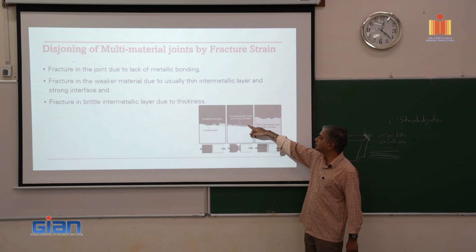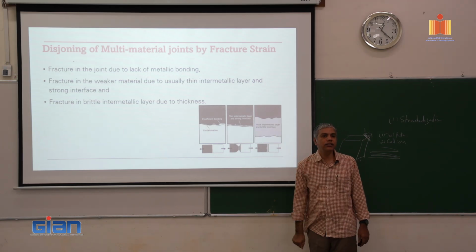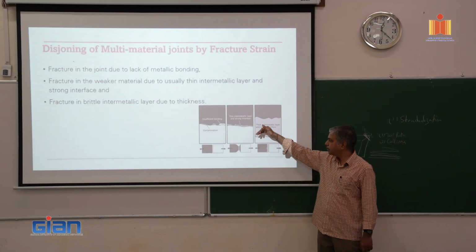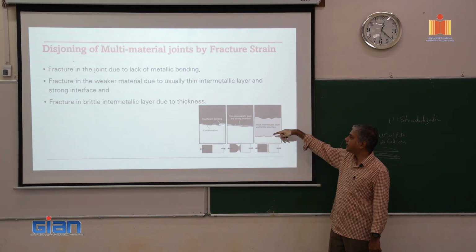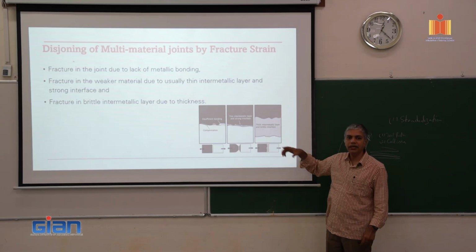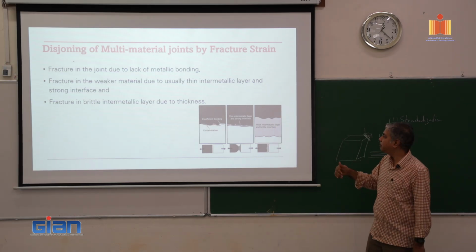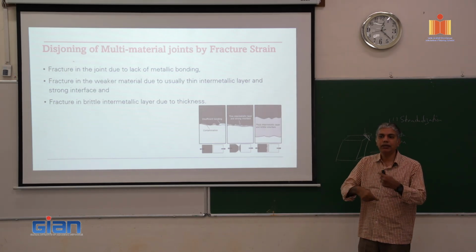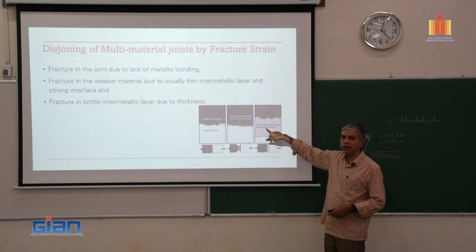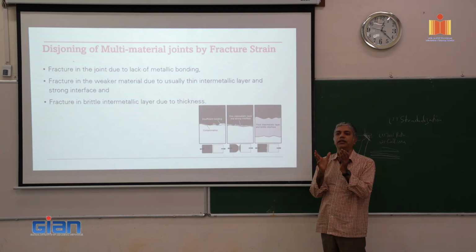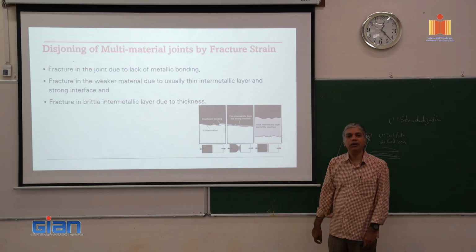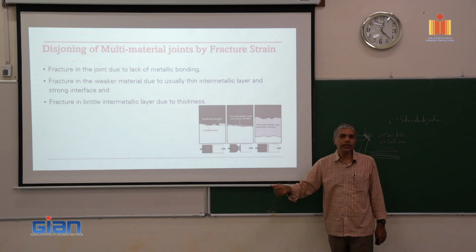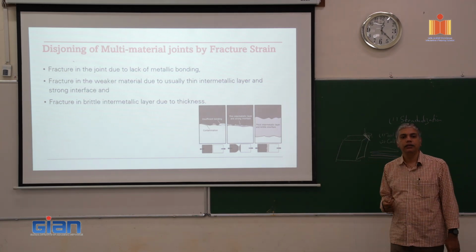In other applications, you also have an intermetallic layer which is formed, which also has a strong interface. So again, how you apply the load there matters. And in some cases you have an intermetallic but much thicker, for example in friction stir welding, where the materials are being fused and mixed together. So the intermetallic is formed, and it is much thicker also. But mostly, this intermetallic layer is also typically brittle in nature. Okay, so what kind of, pardon? Easy to break. Yes, correct.